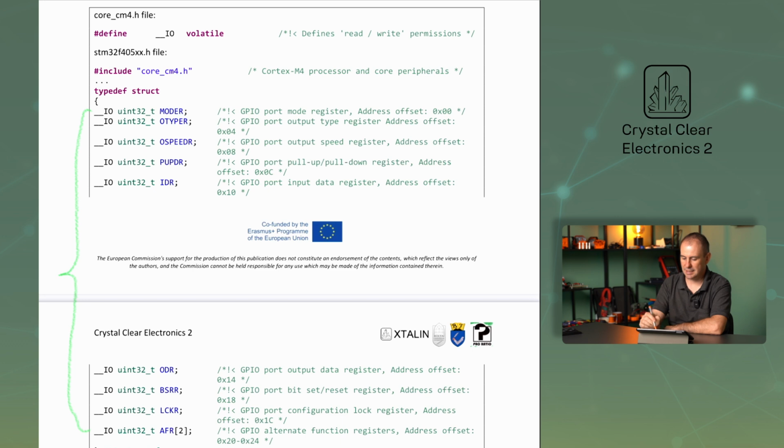Since these 9 registers are logically related, CMSIS organizes them into a common structure. Note that all registers are supplied with the volatile keyword via the I/O macro. With this structure, you can now access all the settings for port D, as well as read and write if it is set to digital I/O. However, if this was all the support that the library provided, we would still have to dig out a lot of information from the datasheet, since we don't know exactly how the bits in each register affect the operation of the device.